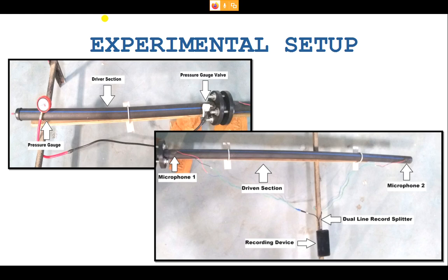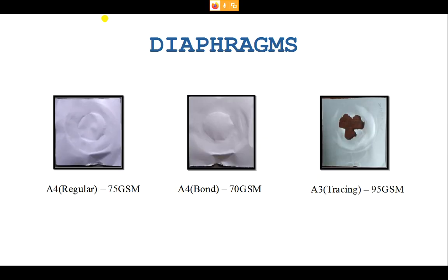So once we have this setup ready, like keeping a diaphragm between two pipes and completely sealing it, tightening it with bolts, we can start injecting air through the left extreme end, that is via a valve, and it is a one-way valve, the non-returning valve. And once we reach the bursting pressure of the diaphragm strength, it will burst and it will produce a shock wave on the right side, and then it will move out towards the open side on the right extreme end. So, if we do one such experiment, what will happen?